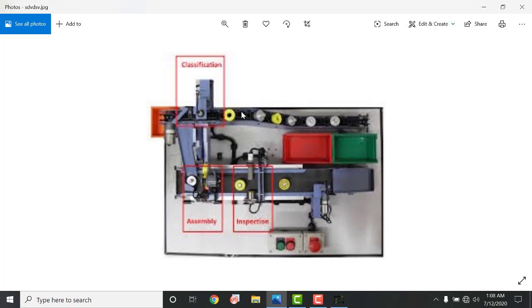For example, your pieces are placed over here randomly, and plastic materials are collected over here in large amounts, so at the end the solenoid valve would not be able to push it because the limit is reached. So at this position an infrared sensor is installed which tells you that you have reached your limit and stops the conveyor belt so that it can stop sending more plastic material.